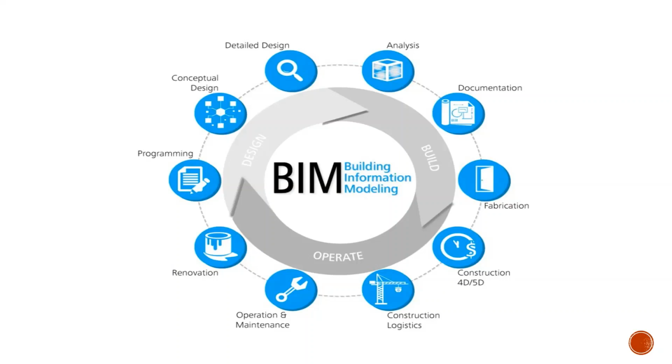We are not just going for that long wall, short wall method. We are not going for that manual method. Whenever we are creating a model on the BIM platform, a model-based quantity will be there. We will be able to quantify everything depending upon the categories that we have provided. It's very easy. And we can divide that into different stages, different phases. If I am going for a demolition or a renovation project, it will be categorized into different phases also. There are a lot of applications for a platform.